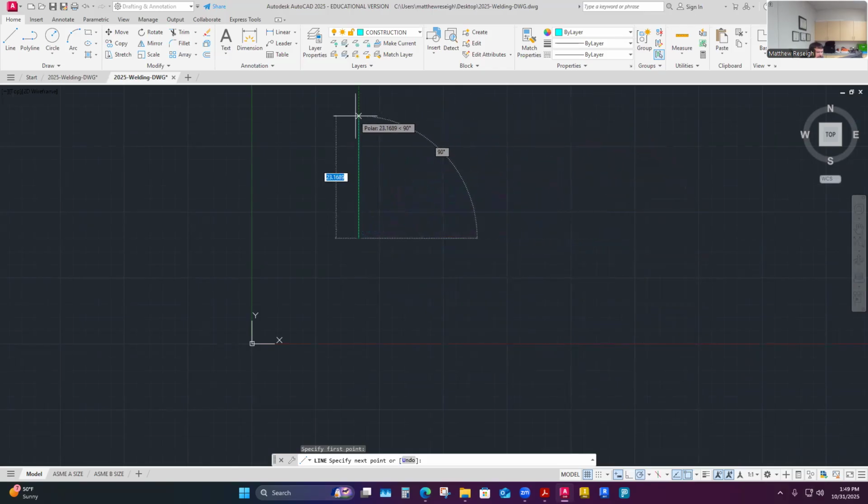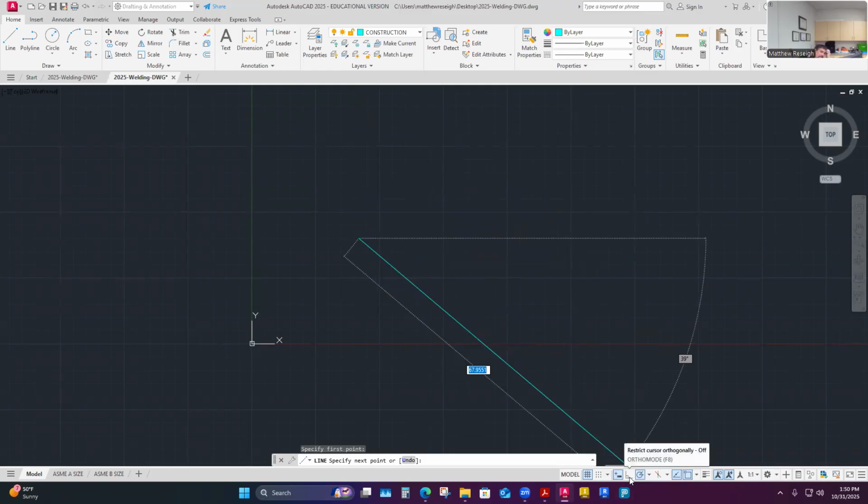and it really helps me stay in orthographic alignment, with a 90-degree straight up and down vertical line and a 0 or 180-degree horizontal straight line. So I use that to my advantage. It's the same thing as turning on ortho mode, which is F8. You'll see me not use that as much, but I have to be careful not to pull things out of orthographic alignment. But I do have this on to help me stay accurate.